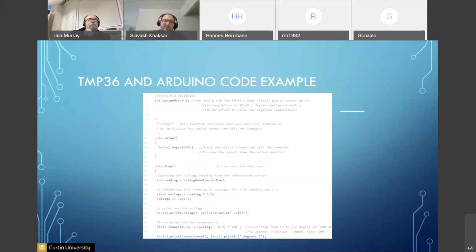And a very, very basic code, because a couple of people asked me how do you usually capture information from a sensor. So I myself usually just capture the information and send that to the serial monitor so I can read it. Later on, to implement a phone app, for example, to send the information wirelessly, Bluetooth or something, that's where I would then pass the information from the serial monitor. You would pass it to your Bluetooth channel and capture it on your phone, or an RF transmitter and receiver situation.